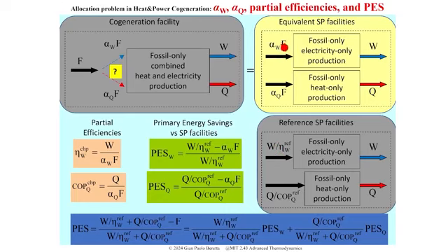You subtract what you actually consume in your cogeneration facility, so that's the numerator, and compare it to the separate production. That gives you the savings of the cogeneration with respect to the production of electricity, and the same for heat. And if you have that number alpha Q, that number is what is needed for the home index, the efficiency index.